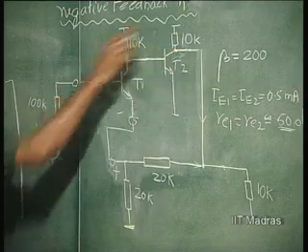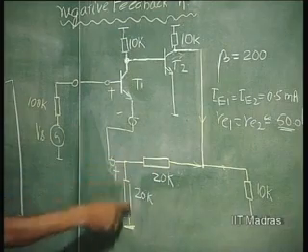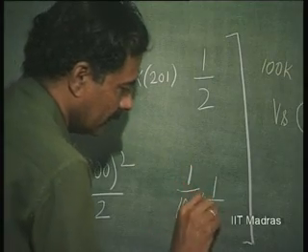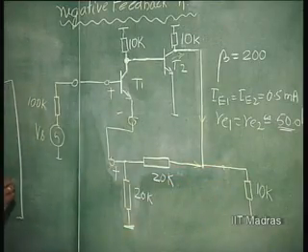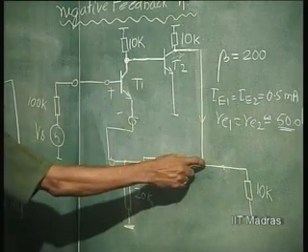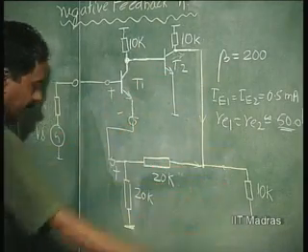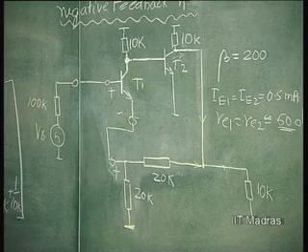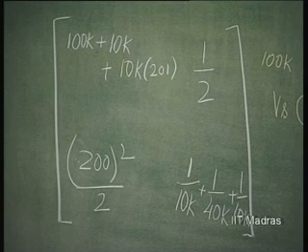and the impedance here is 1 over 10 k, this shunted by 40 k, plus of course this load resistance, which is 1 over 10 k. So, total admittance at this node: this 1 over 10 k, this 1 over 40 k, this 1 over 10 k, total admittance. Here it is total impedance, here it is total admittance. So, that is all. This is the composite H parameter, right.